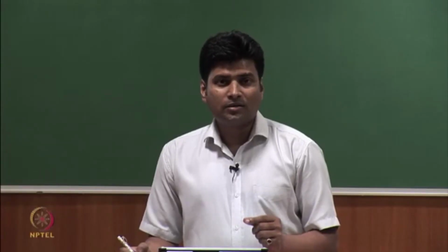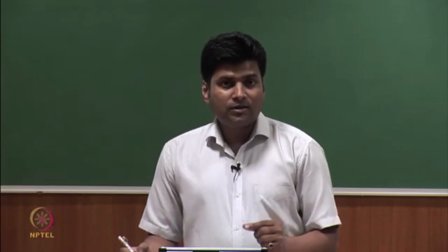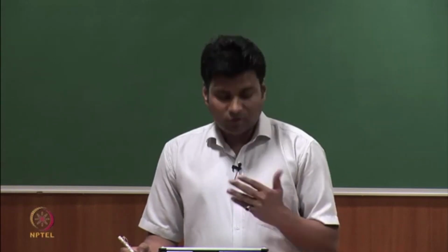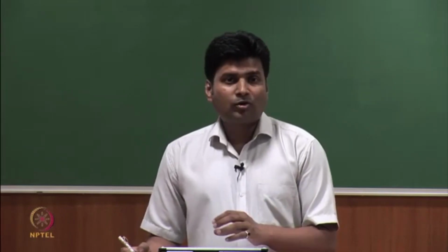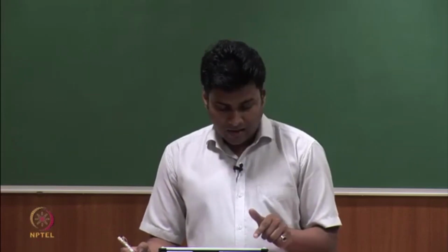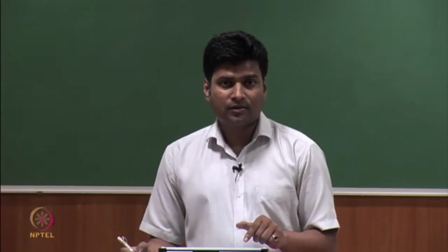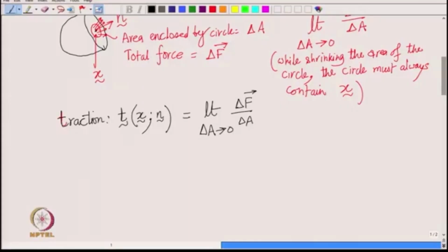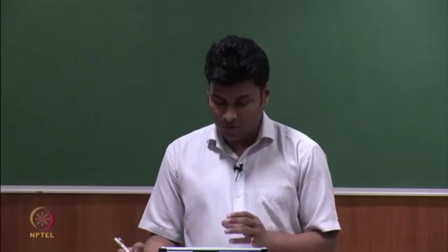Traction is basically telling us what is the intensity of the force with which one part of the body is exerting force on the other part and at a given point x. Okay. And you see, by definition it is force divided by area. So, it has the unit of pressure, but it is not exactly pressure. We will let you know how traction is different from pressure.